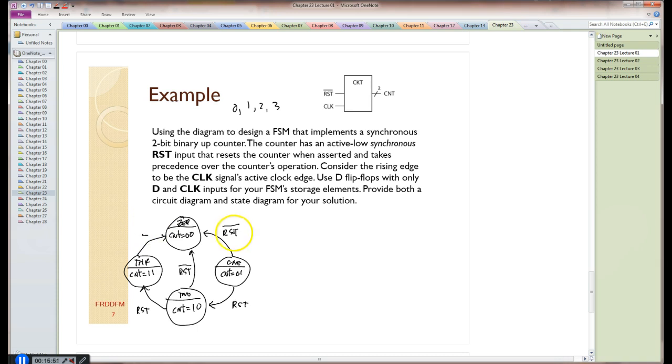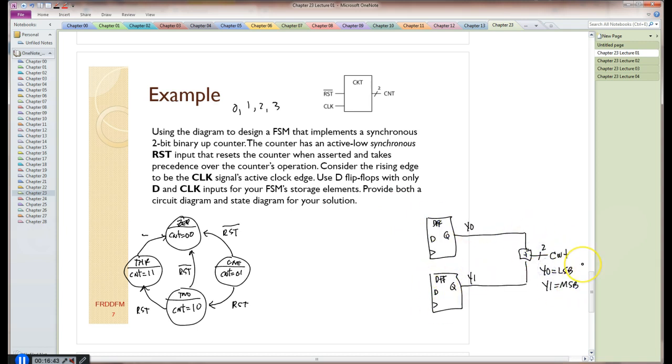So that's really important. Now, you don't always need conditions associated with these states. You can have conditions sometimes and no conditions other times, which is what we have in this circuit. Very similar to the last circuit, we have 2 flip-flops. It's a 2-bit counter. Put some information in there. And so we next need to put some logic in here, which we know from the last problem is going to be a decoder. The issue in this problem is y0 plus and y1 plus. Very similar to the last problem.